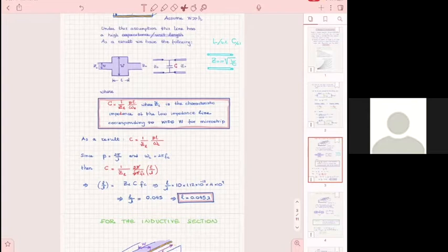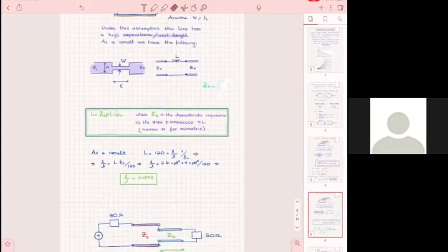No, it only makes a difference for you to remember that if you want to materialize a capacitance, then you always go to a low impedance. And if you want to materialize an inductance, you always go to a high impedance. This is why I put them there. Okay. And I will eliminate them just in case it confuses you. But so you remember.